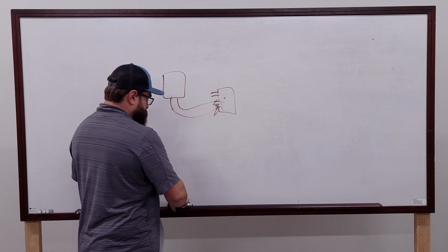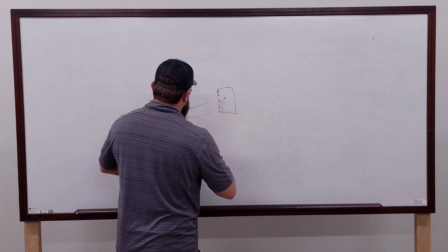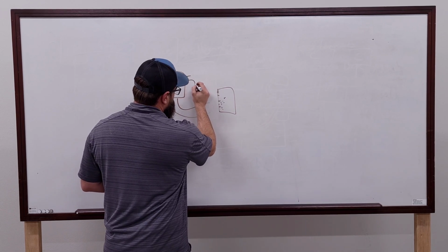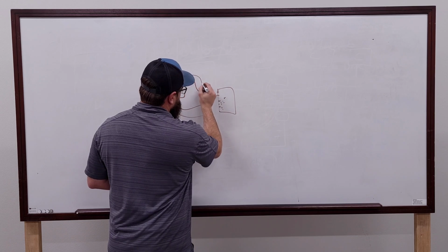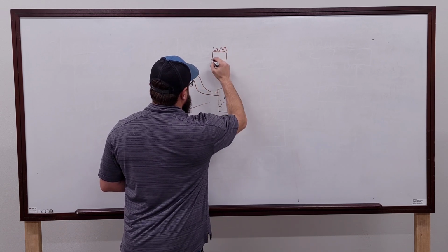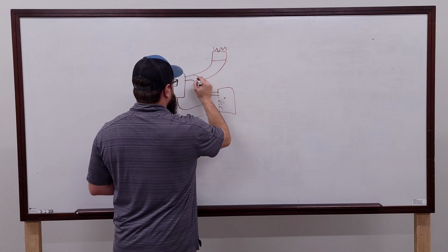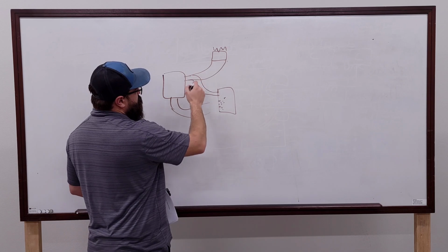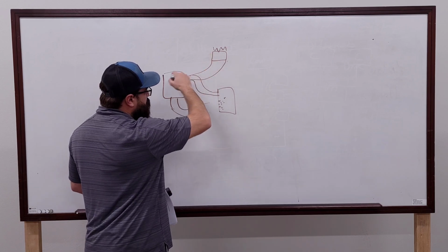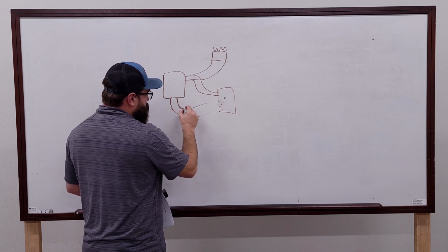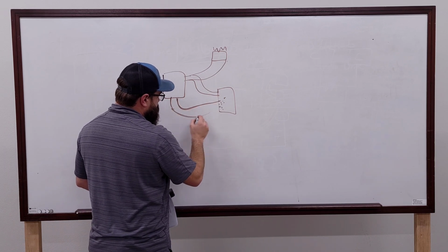Whereas this, let me clean this up a little. So let's say this is our 24 volts, right? Coming from the controller. That's coming from a transformer over here. Okay, so this transformer powers the controller, and then it may be jumpered from up here, it may be coming straight from the controller. That feeds power to here. Then out of our controller, we have our 0 to 10.